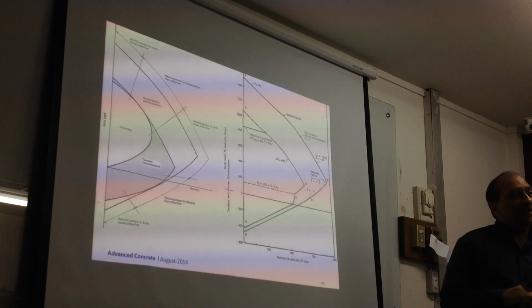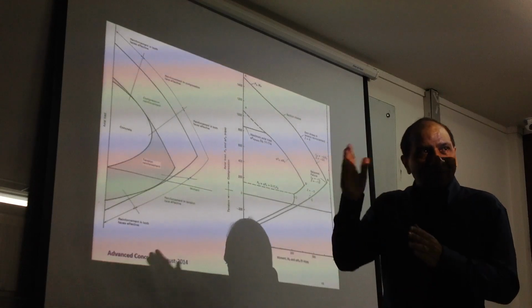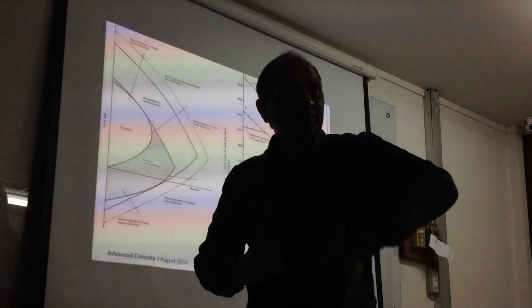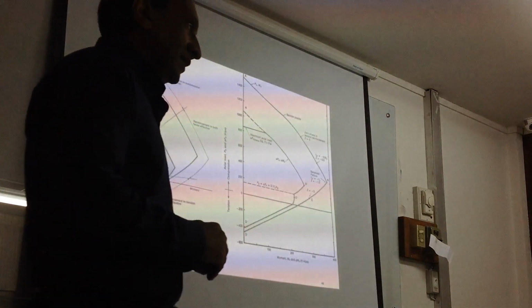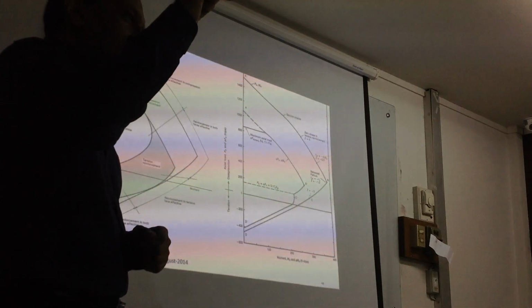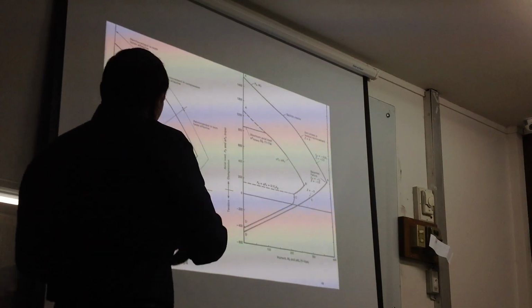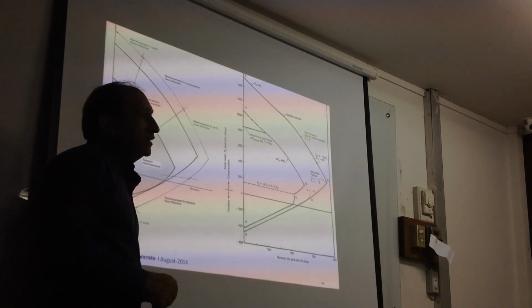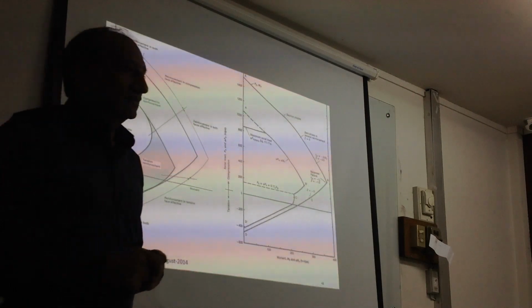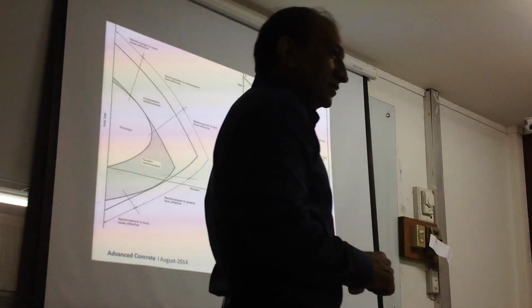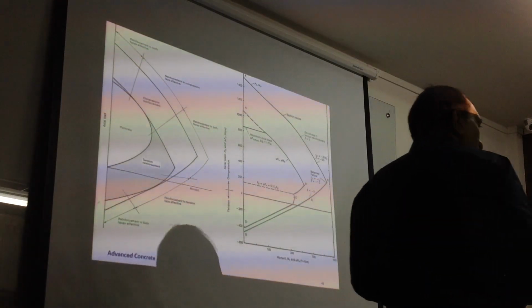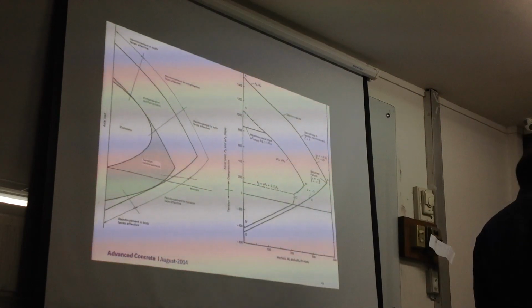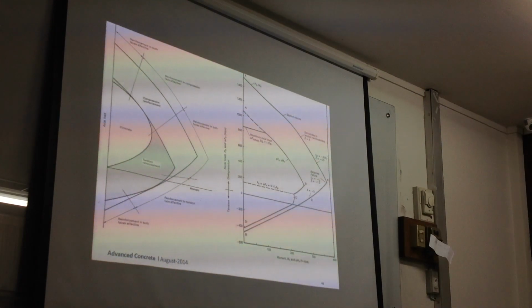That is a very important point for us because on one side compression will govern, on the other side tension will govern, right? So the balance point is important to calculate. And then there is a point when all the reinforcement is yielding, the tension case. So you have all these nice points on the curve which define clear areas.